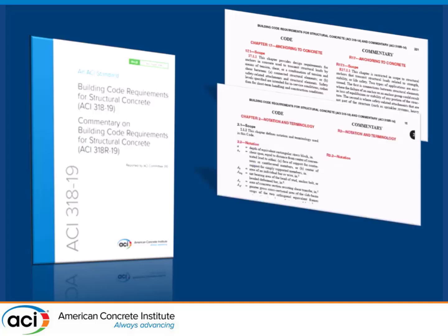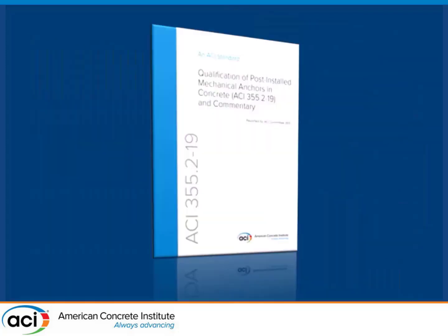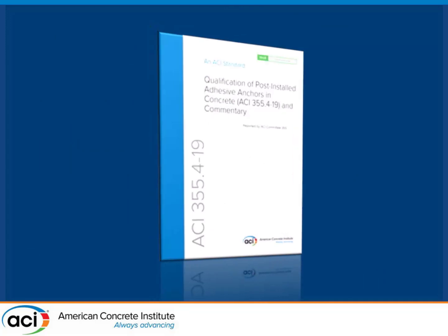Now, it leans heavily on Chapter 2 for definitions, which we'll talk about. And then, for those who are not very familiar with ACI 318, Chapter 26 holds all the stuff that we want to put into a specification. So the specification information that is most important to ACI 318 is all shoved into Chapter 26, and yes, there is a section on anchorage to concrete. So those are the locations in 318.19 that you should go back to as far as following the code for anchorage design. You'll find constantly two other documents, 355.2 and 355.4.